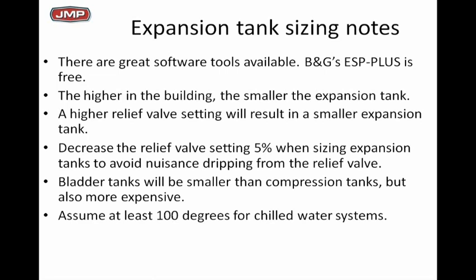Another little tricky piece: we've always recommended that on chilled water systems, use 100 degrees as your max temperature. And you say, well, that's chilled water. Yeah, but using 100 degrees, you'll get a tank on most systems 15, 20 gallons bigger, no big deal. The other piece is, how many times is it possible for a large system to lose power? If you lose power on a hot August day, the 45-degree water is going to start warming up. Will it ever get to 100 degrees? I doubt it, but you want some little safety factor there.